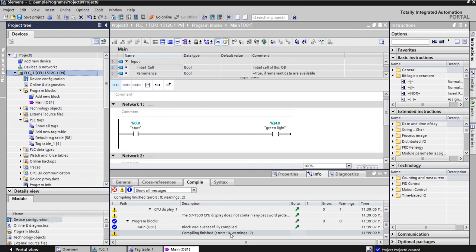Then once that was created, we had to fix the IOs. You will have to do this every single time you make a program. You will change the digital inputs, at least for what we're working on, to 0 to 1, and the outputs from 4 to 5. But remember, the analog is stealing the one we need, so you need to change the analog input to like 126, so it's not even close to anything we're using.